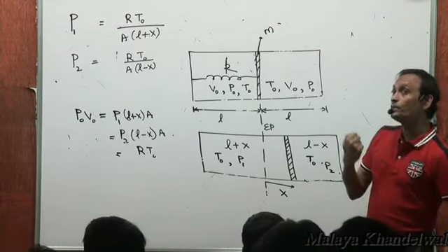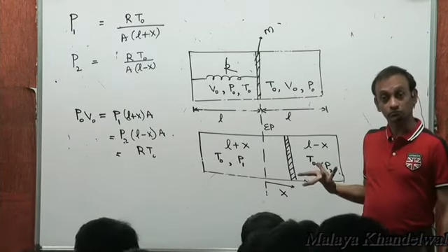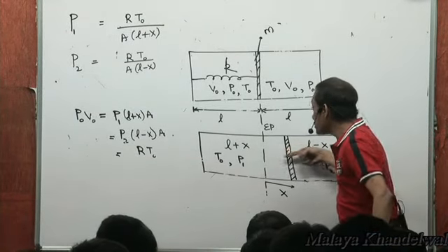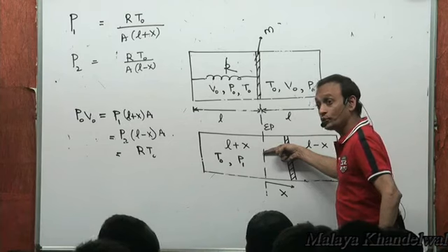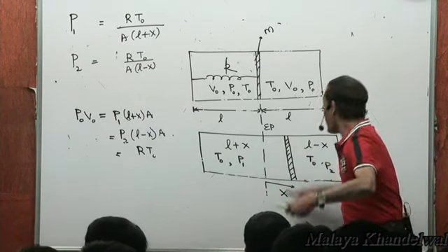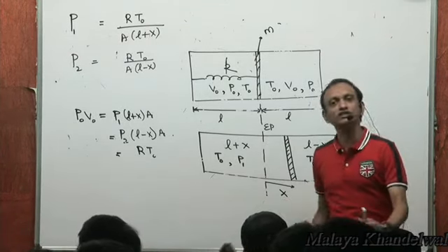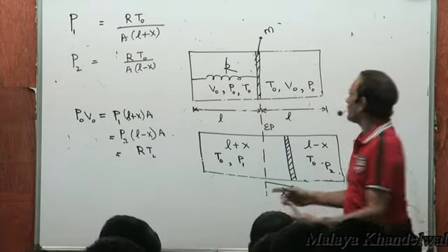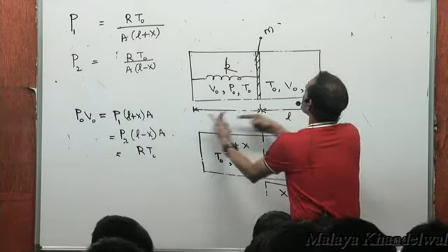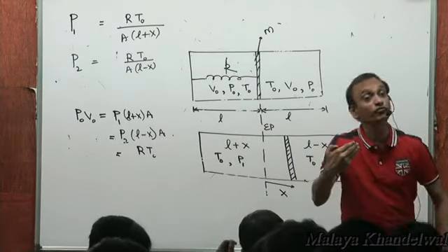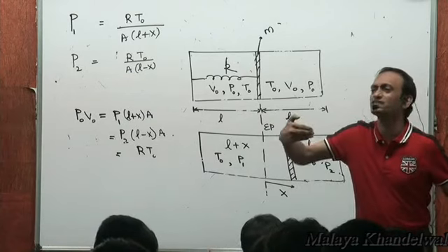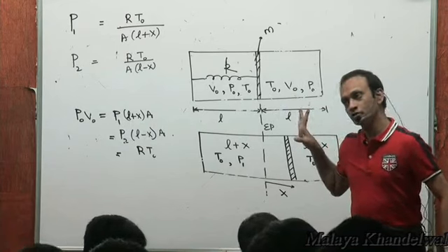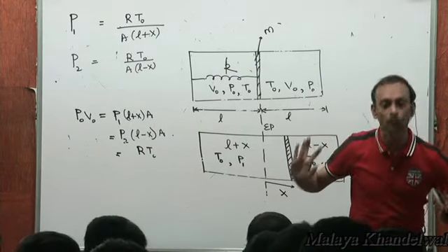Now let me look at the free body diagram of the piston. I want to show that the net force acting on the piston is leftwards, directed towards the equilibrium position, therefore restoring in character and proportional to x. If I can establish that, I will assume that x is small compared to L, because it's given that these are small oscillations. That means x is small compared to the other dimensions in the problem, and eventually, if required, we'll use that.